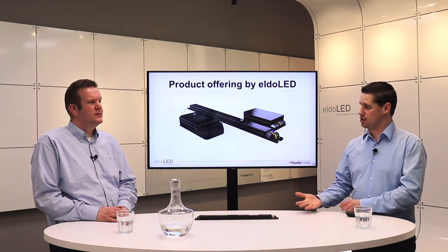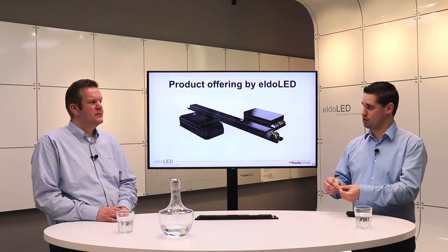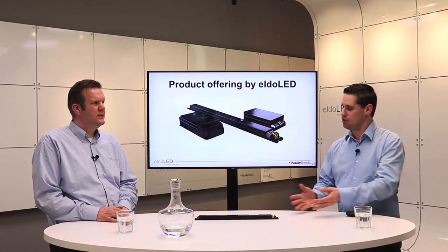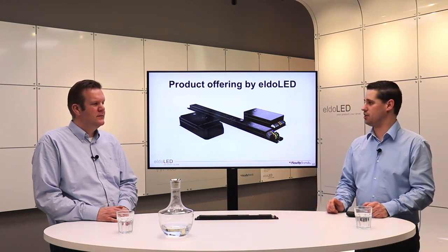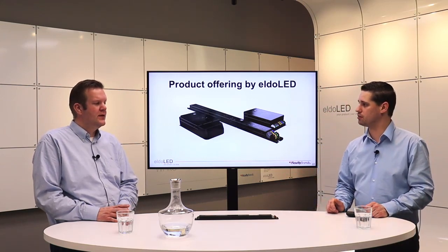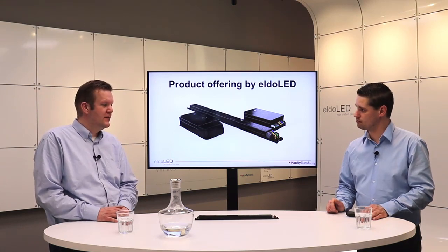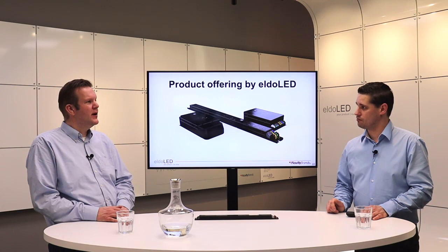So doing that up front means that you can connect the cables up front, add the wire ferrule, and later on stick them in the driver, avoiding any shorts in the cabling. So it makes sense. So you avoid T-taps and you have a secure connection, easy to produce your luminaire in.